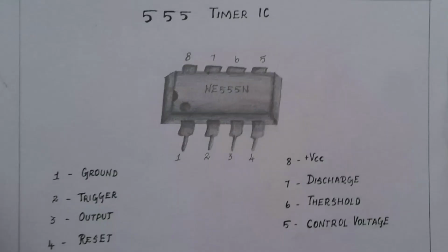In any 555 IC, it is basically a monolithic timing circuit that produces accurate and highly stable time delay or oscillation when compared to applications of operational amplifier. In some areas, a 555 IC is also equally reliable and is cheap in cost. Apart from monostable multivibrator and astable multivibrator, a 555 timer can also be used in DC to DC converters, voltage generators, and so on. It is used in the temperature range between 0 to 70 degrees Celsius.